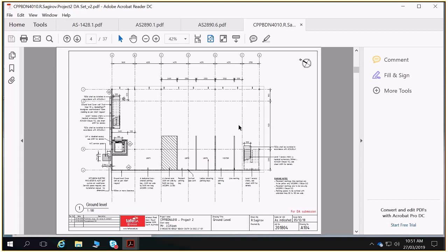Beyond that, with our car parking underneath, we have to enclose two sides of that, and it came up in the discussion earlier on. Okay, does it end up making it a Class 7 or a Class 10 building? Possibly, if we really want to answer that question, we can pore through that a little bit later today. Have a look in the NCC specifically at those definitions. But the intent of this project, as written for the subject, is that it makes that car parking area underneath a Class 10 structure.